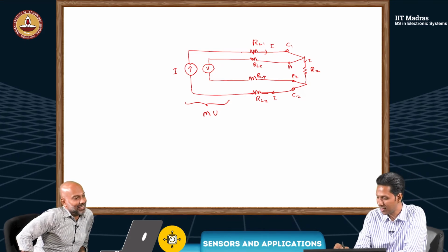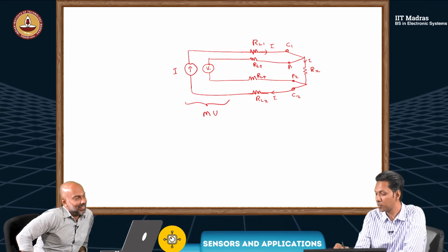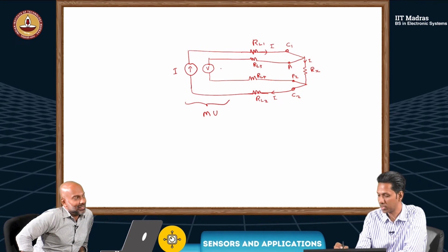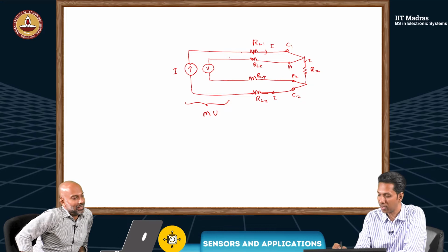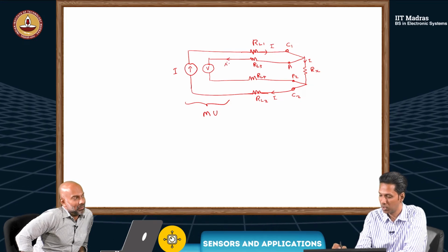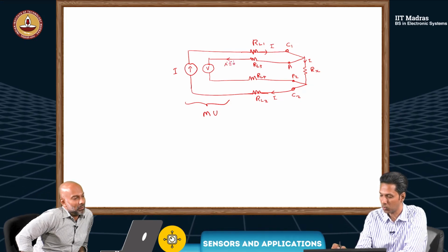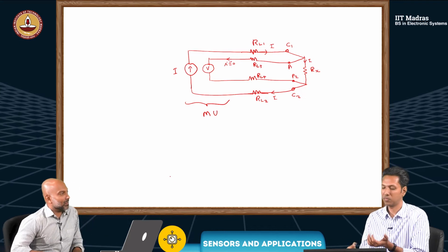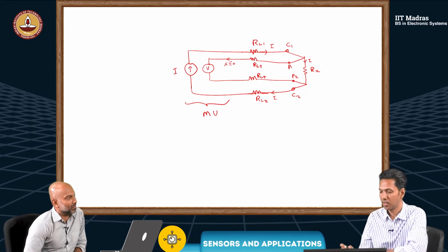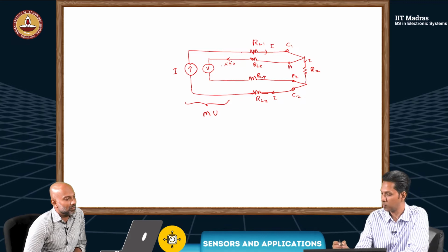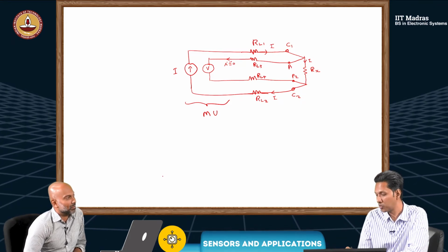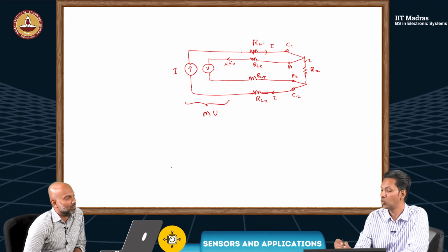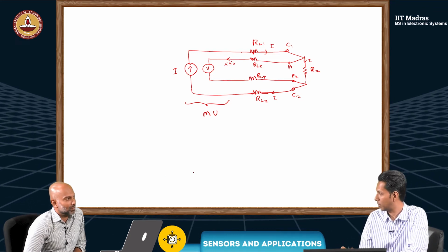Because this voltmeter, or the system that I use here to measure, has very high input impedance, the current drawn by this will be almost 0, minimal. It will be some mega ohm or large resistance. So I am not drawing any current from these P1, P2 terminals. So that way the lead wire resistance effect is removed.